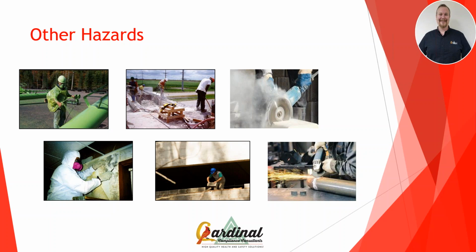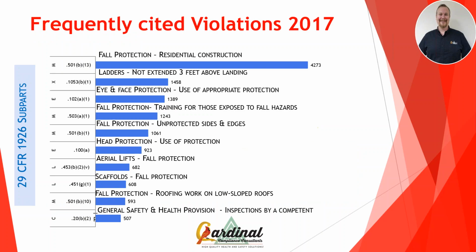Using a jackhammer, using a lot of the tools that are just a part of our trade, that's a lot of vibration that goes into our hands. And there are permissible exposure limits for vibration with the tools that we work with. That's something a lot of site plans don't address. A lot of companies, a lot of safety people, and I'm guilty of this too, don't think about. And what about silica or biological hazards, or just tool use, the tools of our trades? There's a lot of hazards within construction outside of the Focus 4, and these are things that you have to take into account throughout the life of a project.